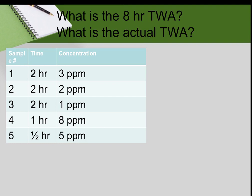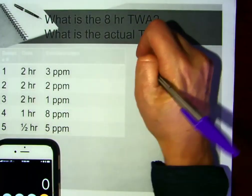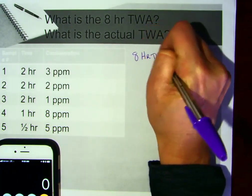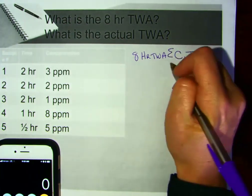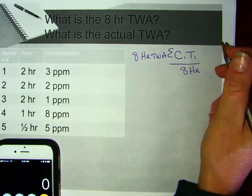So this would be an opportunity to review these calculations and do a short example. Our problem: what is the 8-hour time-weighted average? Our formula for an 8-hour time-weighted average is the sum of concentration times time over 8 hours.